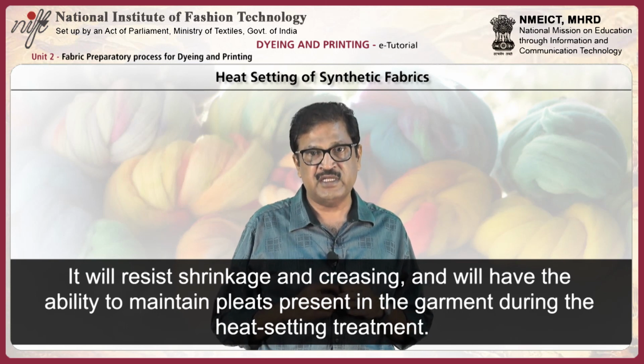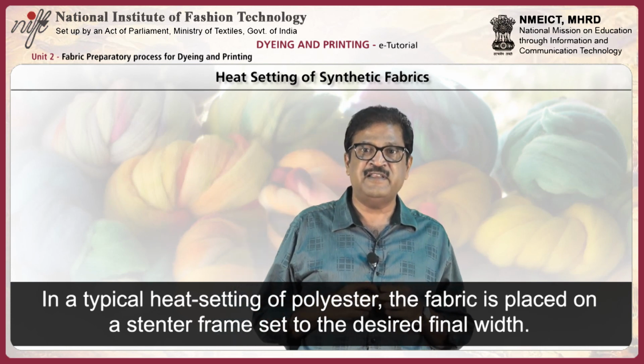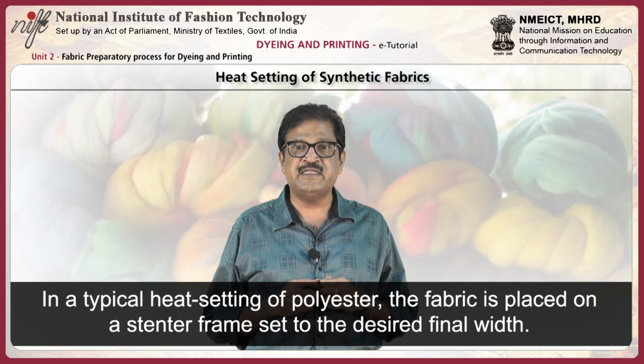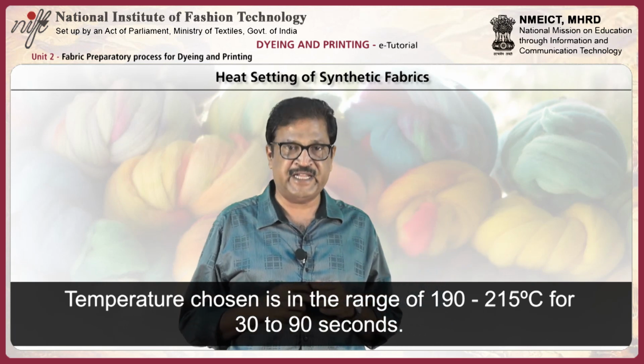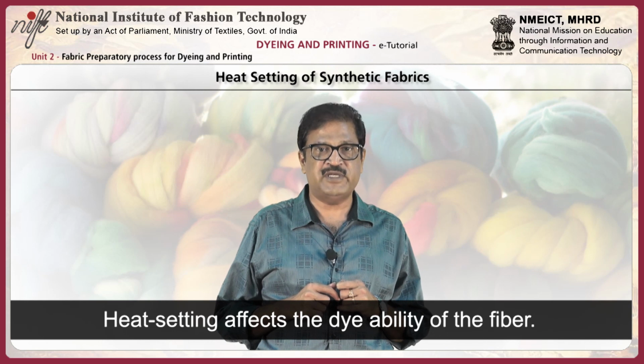In a typical heat setting of polyester, the fabric is placed on a stenter frame set to the desired final width. The temperature is maintained in the range of 190 to 215 degrees Celsius for 30 to 90 seconds. Heat setting affects the dyeability of fiber.